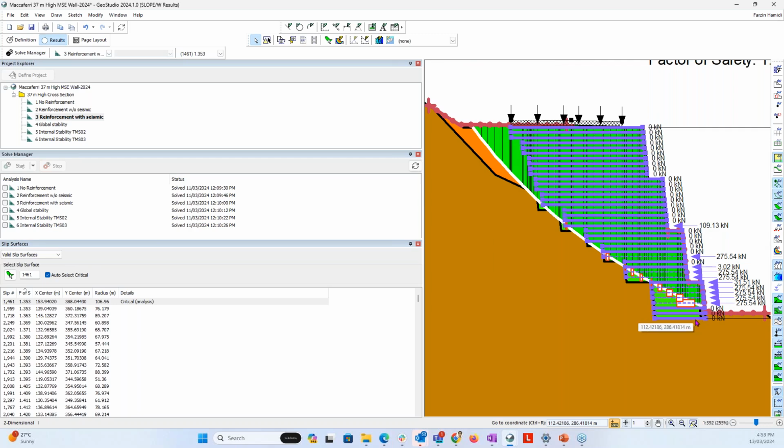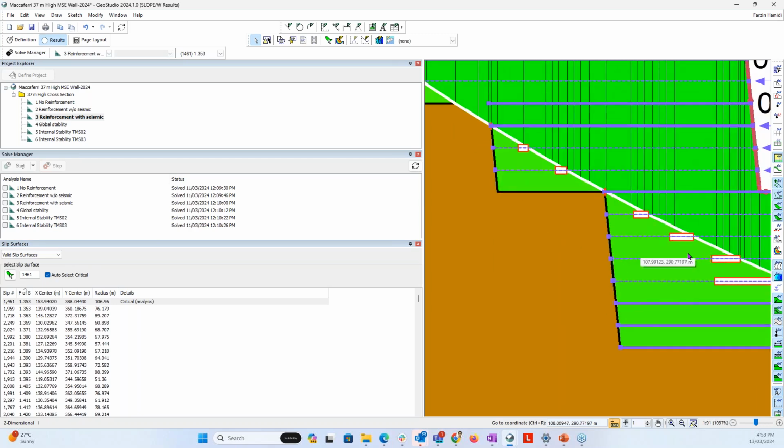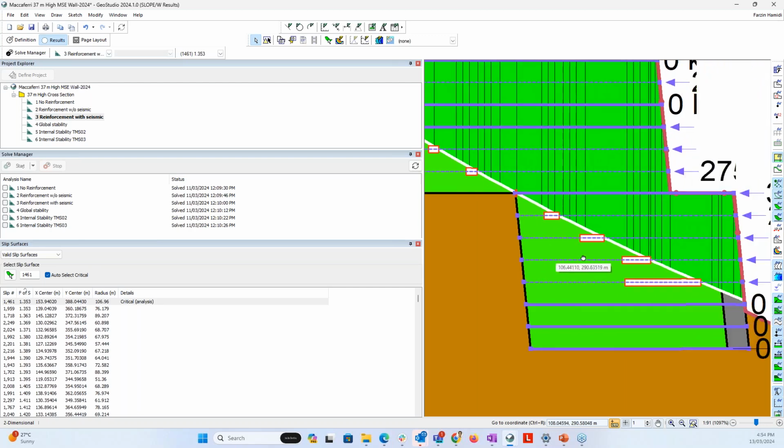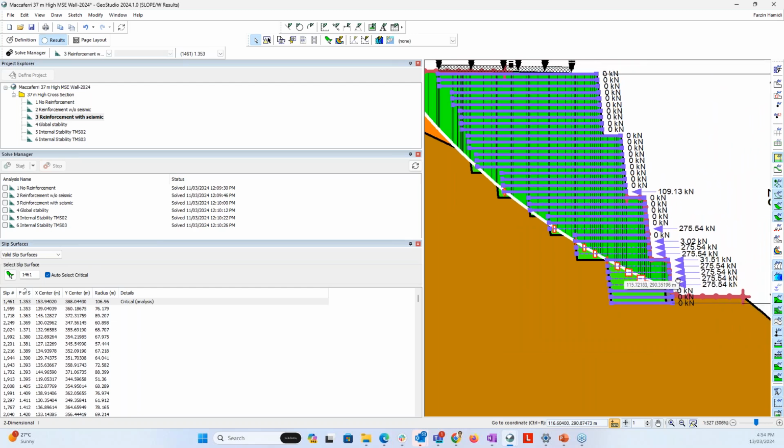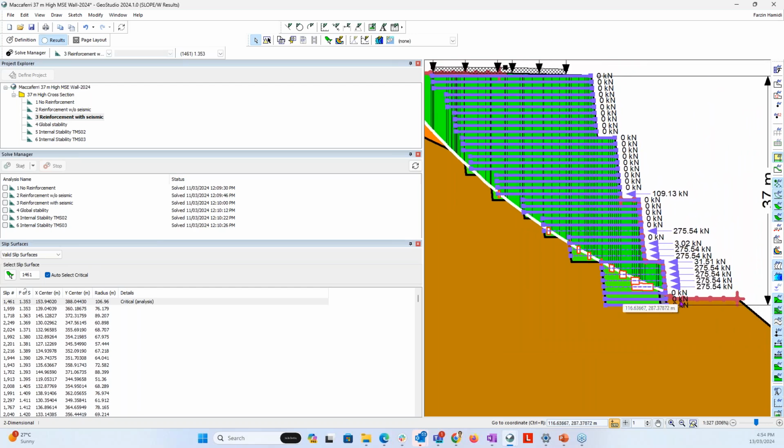And some of you asked, some of these geogrids are failed with a tensile capacity. So the failing doesn't mean that the geogrid is not activated anymore. The maximum capacity of that geogrid is going to apply to these slip surfaces, because as I mentioned, the limit equilibrium analysis is mainly talking about the force equilibrium.